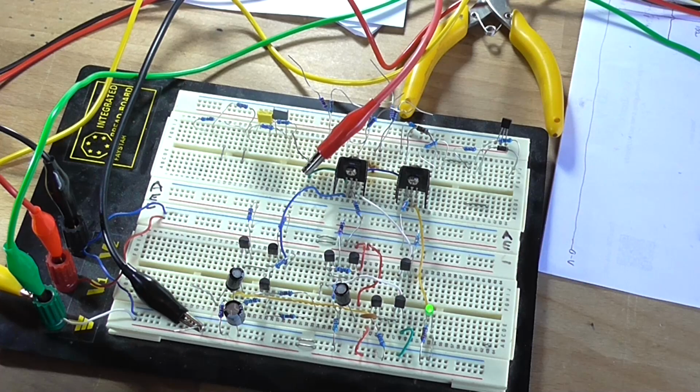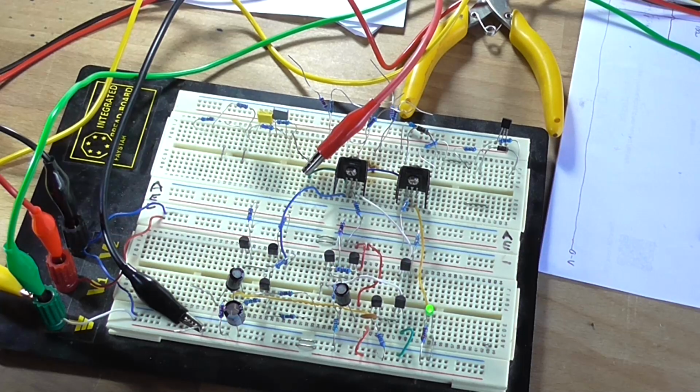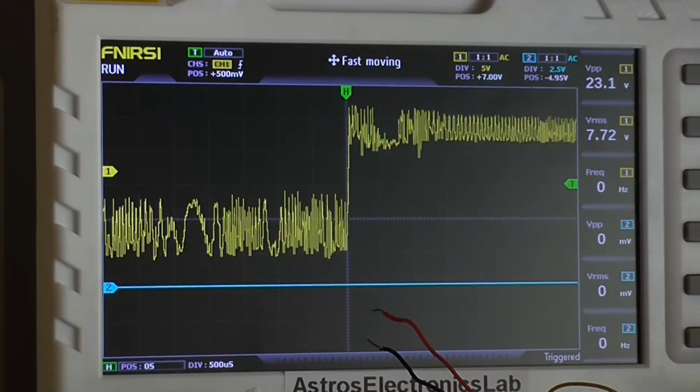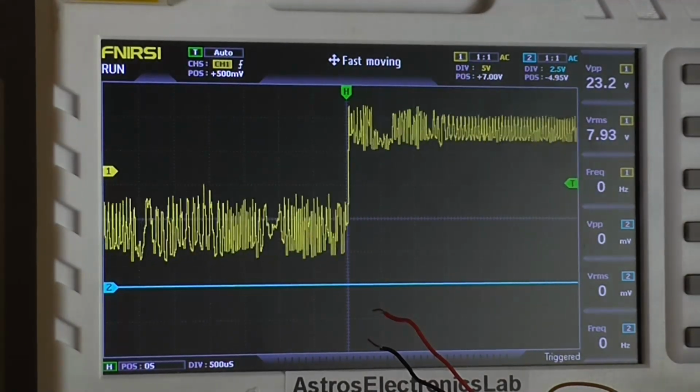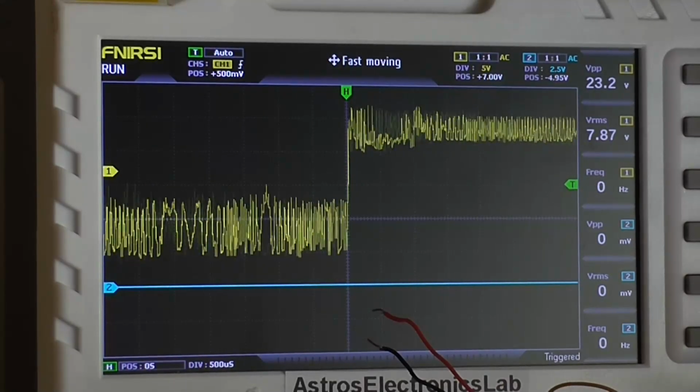So before loading the thing, I think the best course of action here is to hook it to an oscilloscope unloaded and just see if we're getting any signal output. Yeah, it doesn't seem to like that. It appears to be oscillating, so I might try putting some bypass capacitors in the supply lines and see if that disappears. But that's not right.